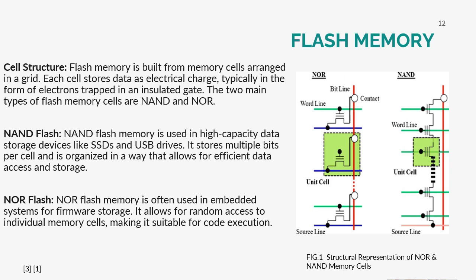Flash memory can be divided into two types, NAND flash and NOR flash, and these two major flash types are dominant in the memory market. NOR flash has lower density but a random access interface, while NAND flash has higher density and interfaces access through a command sequence.